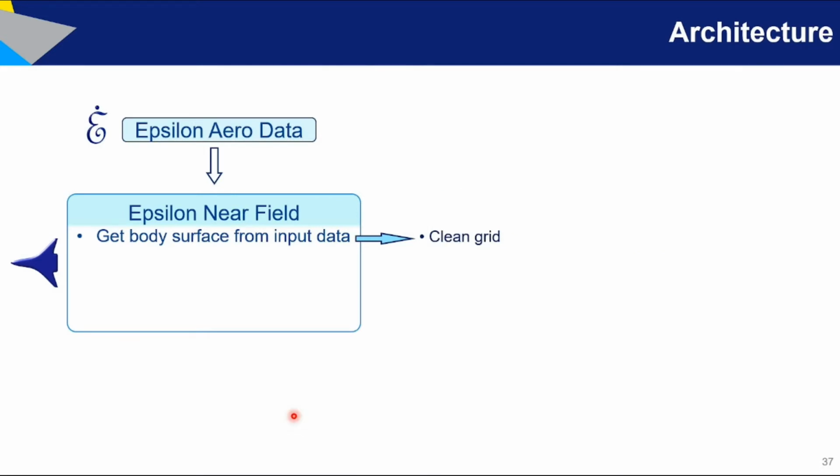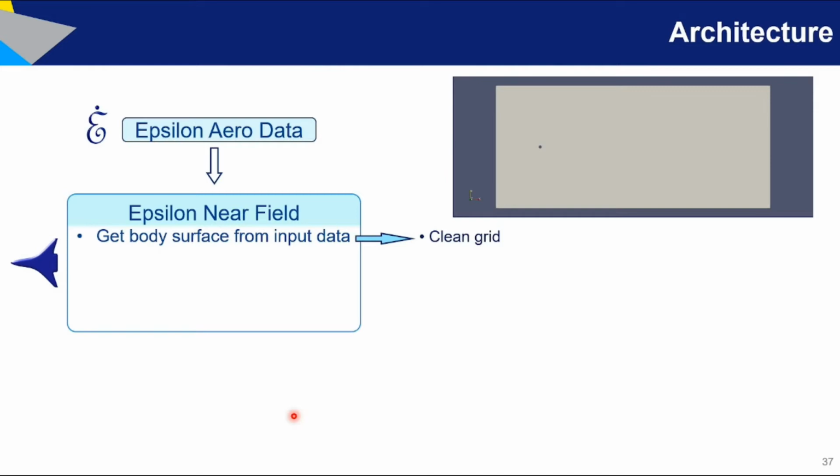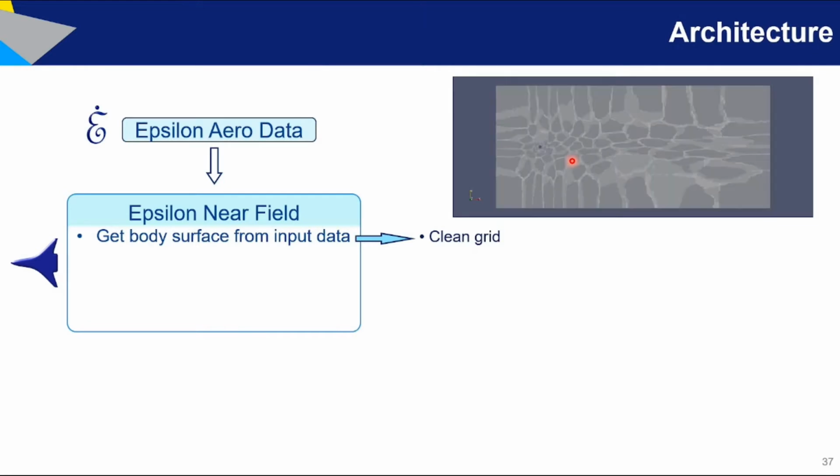Well, once the body is extracted, in some cases you have to perform an extra operation known as clean grid. What is that? Well, in some cases, especially if you're performing a multiprocessor simulation on a server, you start from a single block CFD domain, but when you run multiprocessor, the solver splits the entire domain into multiple small domains to assign each domain to each processor.